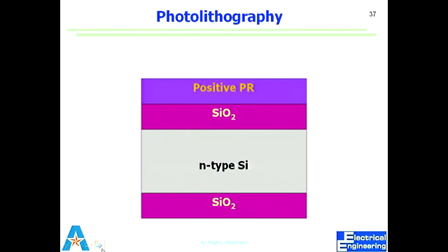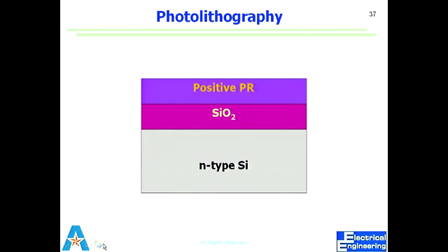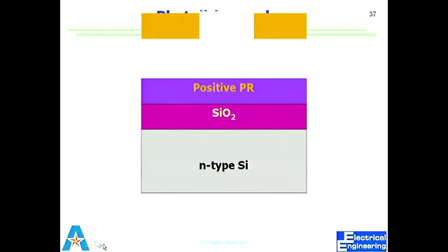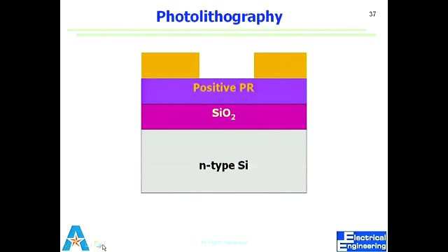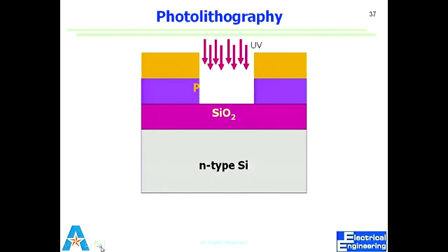So I may or may not remove silicon oxide from this, but I use a mask which has certain regions which are opaque for UV, certain regions which are transparent for UV. UV shines through. Wherever it shines through, the resist undergoes chemical changes, right? So resist has chemically changed. I shine it, I should remove my mask first, and of course I shut off my UV.